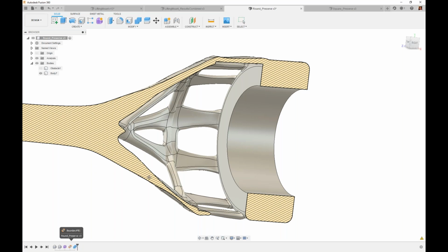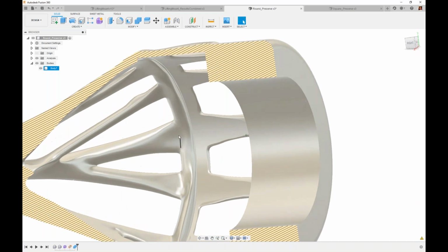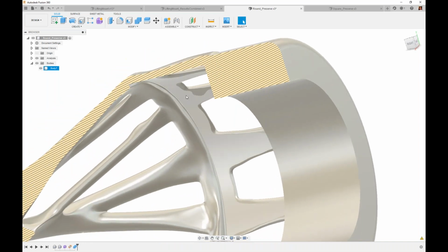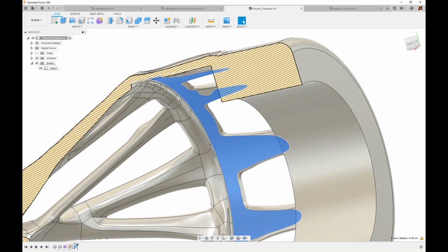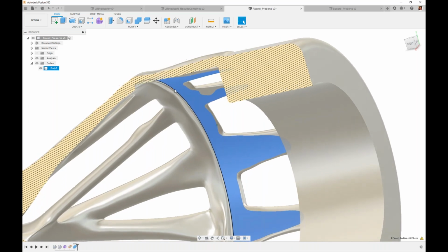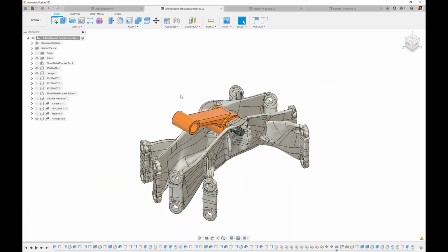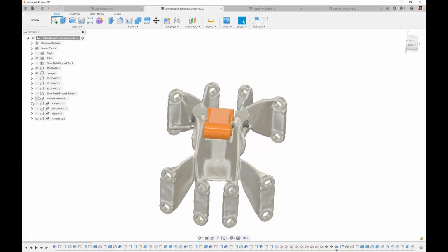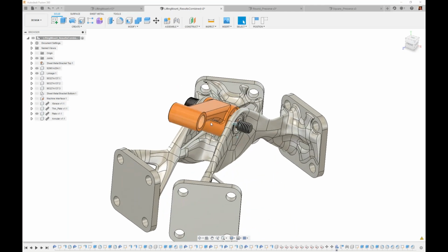If you want to keep it, you can, but again, in some cases you can see that final cutout is creating some additional surfacing. And in this case, since it was a sharp cornered obstacle, a sharp corner into my geometry, that's going to be a location for stress concentrations. If I switch over to, so this is some of the outputs that I got from my model that we were just talking through.